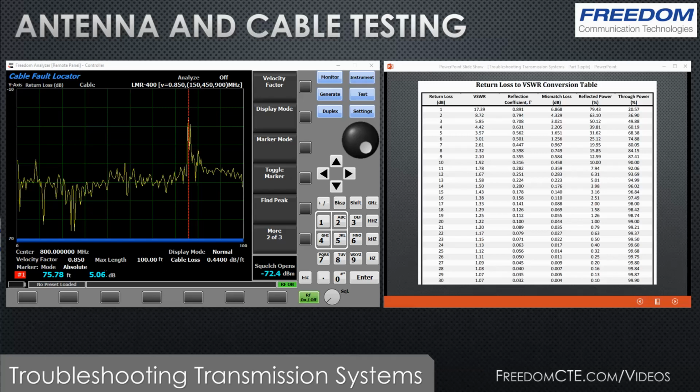And now I'm going to show you that we can also determine the total loss in the cable. It's being hidden from us at this point because we are accounting for cable loss in the calculation of the return loss. But if I tell it to not account for the cable loss, we can actually look at how much power is being lost just in the cable. For that, I'm going to go back to an open circuit and turn off the compensation for the cable loss.